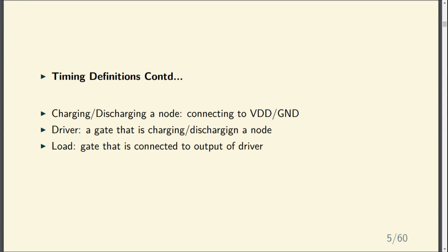Generally nowhere in the circuit will you see two signals that have the same driver, because there will be some conflict. I have one output that is maybe going to 0, and I have another gate driving the same signal to 1. That will be a problem. It will be at an intermediate value, and that is a huge problem. So generally every signal will have exactly one driver circuit, and not 0 either, because every signal has to have a proper value, 0 or 1.